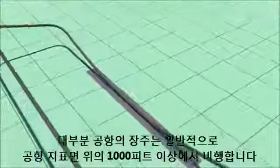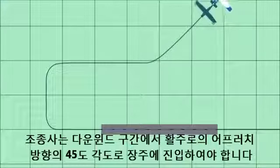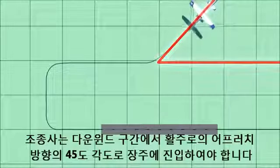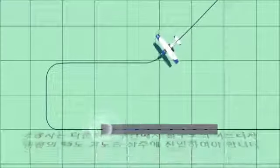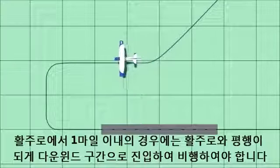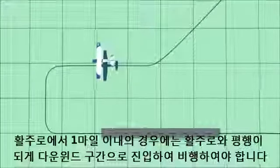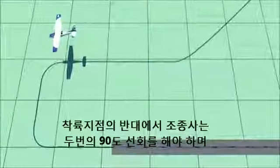At most airports, the traffic pattern is typically flown 1,000 feet above the elevation of the airport. The pilot should enter the pattern on a 45-degree angle to the downwind leg, flying towards the approach end of the runway. When within about 1 mile of the runway, a turn should be made to enter the downwind leg, flying parallel to the runway and in the opposite direction of landing.